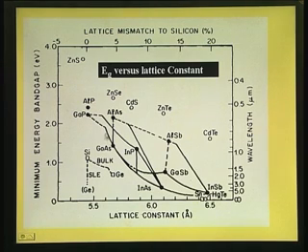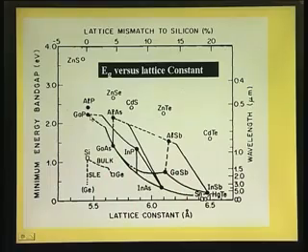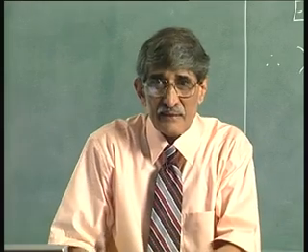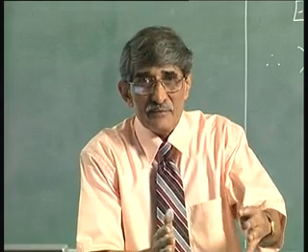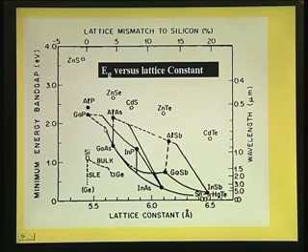if you see that, this is solid line, implying from gallium arsenide is direct band gap. If I go on adding phosphorus to that gallium arsenide, it becomes more and more towards gallium arsenic phosphide. If you go all the way down, it is gallium phosphide, that becomes indirect band gap. That means, from the direct band gap material, it will move towards the indirect band gap semiconductor. At some point, it will become indirect. For example, there it becomes indirect. Beyond that point, if I move, that dotted line indicates that that will be indirect band gap.